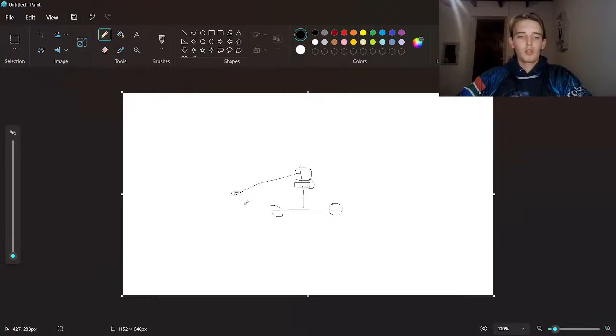Now the normal use of this arm would be, it would have a position over here, which the encoder would call 0. This is where the arm starts. So the encoder in this motor will say the position of this right here is 0. Normally you'd want this position 0 close to the ground. You grab stuff off the ground on the mats or whatever, and then you have a position to deposit it on whatever goal you need to. Like in Center Stage, you would have had to drop it on the backdrop.